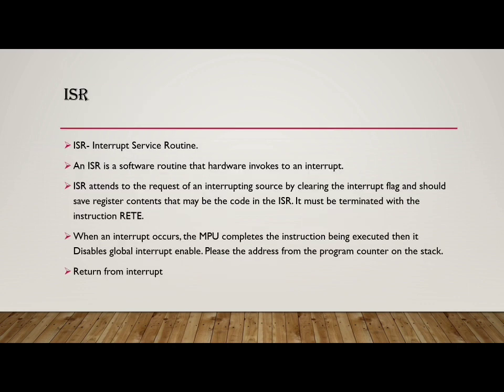ISR, we have discussed just now only. ISR means interrupt service routine, and ISR is a software routine that hardware invokes in response to an interrupt. ISR attends to the request of an interrupting source by clearing the interrupt flag and should save register content that may be changed by the code in the ISR. It must be terminated with the instruction RET.